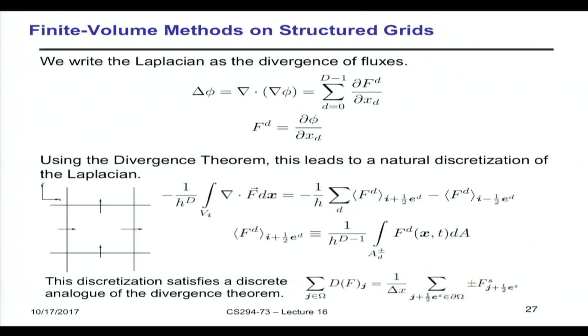So instead, you integrate this over a domain, which in this case is just a box, and you end up with this representation of a difference, where the angle bracket there means the average over the face. So when you've done that, you basically have a nice way of discretizing any domain. This is just a square rectangular domain, but it basically respects the physical properties, which is that the heat goes as a gradient, and whatever was in there has to reduce by the exact amount that left.